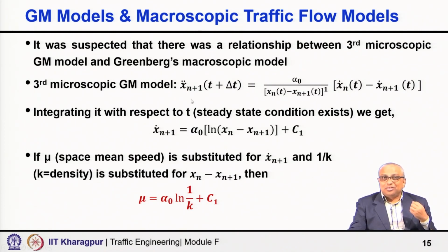So, let us take the third generation microscopic model, remember it is a microscopic model whereas Greenberg is macroscopic. Can we really get Greenberg's model from this General Motors third generation model? That was the attempt. So, what if you integrate this with respect to t under steady state condition, where x double dot is acceleration.